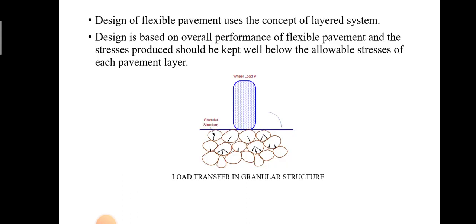Design of a flexible pavement uses the concept of a layered system. Design is based on overall performance of the flexible pavement, and the stresses produced should be kept well below the allowable stresses of each pavement layer. This is the figure of load transfer in a granular structure.